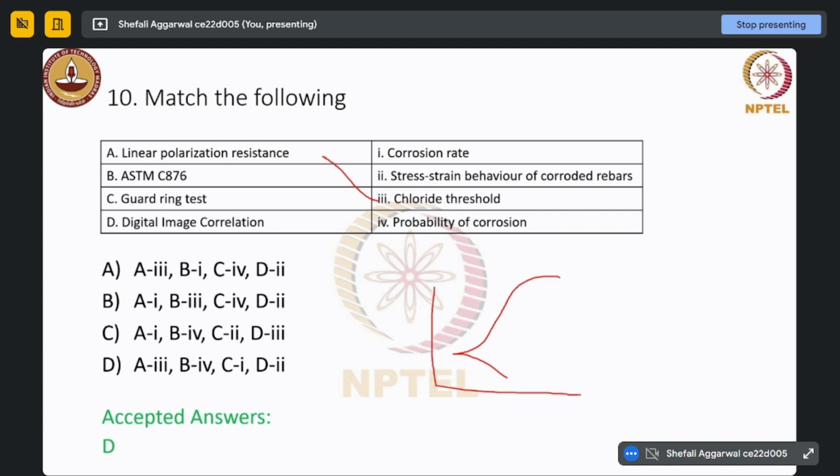For that we need the pore solution. We need the pore solution for the LPR test also. We use steel in concrete or mortar for LPR, but for this test the electrolyte we are using is the pore solution. Okay, so you are telling we are doing steel in solution, right? Yeah, this test is mostly done by immersing the corrosion steel specimen in the pore solution.